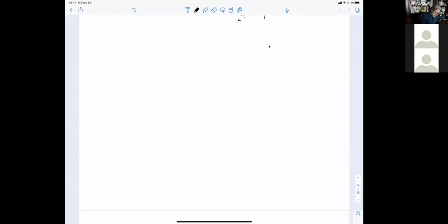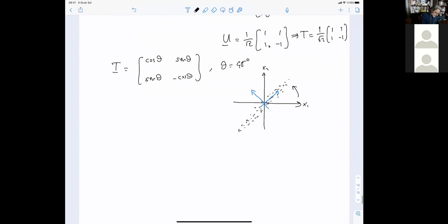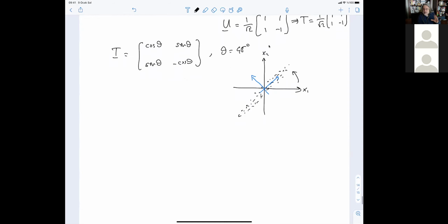Okay, now, the last thing that we did was the development of the optimal transform called the KLT, the Karhunen-Loève transform. And in the 2x2 case, we found the solution. For larger autocorrelation sequences, of course, it needs a little bit more attention. But the thing that is interesting regarding the eigenvalues and the eigenvectors is the following.